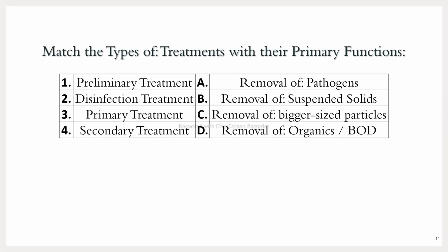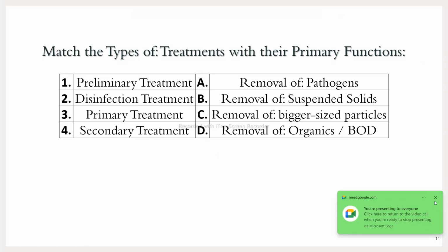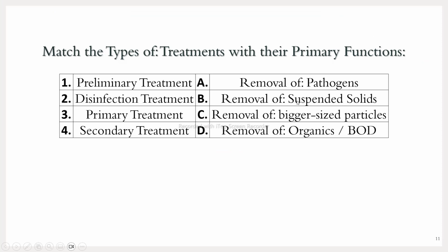Okay, in the meantime, for your information, I will tell certain other things. You see, chlorine removes the pathogen from the water by forming a free radical, and with the help of that, it destroys the cell membrane or cell wall of the bacteria, and it disinfects the water if the pathogen is present inside the water. And chlorine has certain advantages and disadvantages.